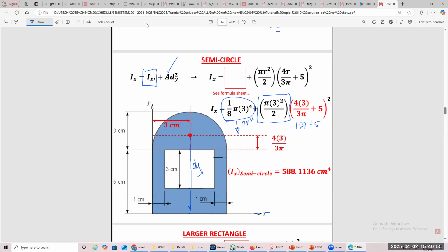And it's going to be rotating around which axis? Around here. Right? Around this axis, you're rotating around that axis this time around. It's the x-axis you're rotating around. So that becomes your d, and it's different from the centroidal axis. The centroidal axis would have been where the 3.8 is. So it's not around that axis you're rotating. So you have to look for the particular axis that you're asked to rotate it about and find the d related to that. So it's 1.27 plus 5, and you get that distance there. Any question there so far, guys? Is that clear?